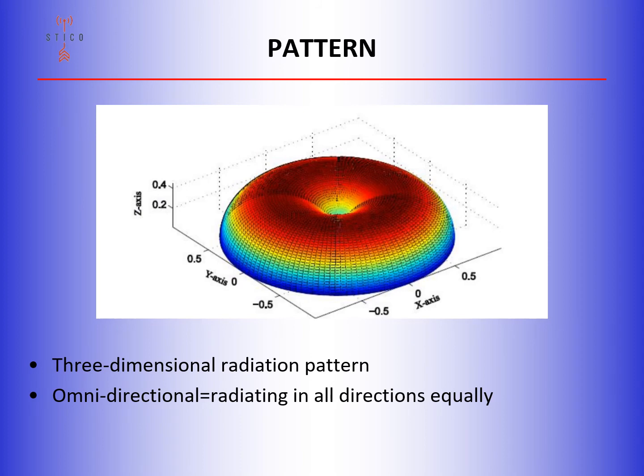The antenna pattern is a 3D representation of the amount of energy directed along the horizon from an antenna. Notice in this example of a quarter wave how the energy radiates out equally in all directions. This is called an omnidirectional pattern. An omnidirectional antenna is desired for mobile applications, since you never know the direction of your transceiver antennas that are going to be receiving the signal.